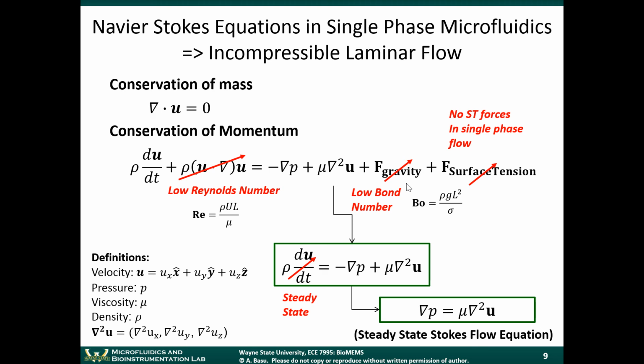So remember, with the Navier-Stokes equations, you can imagine packets of fluid moving through a channel. If you could add energy into one of those packets of fluid somehow, then you can get the fluids to move. So we're going to talk about dynamic micropumps, which are basically based on that principle. You add some type of additional force in addition to just what the Navier-Stokes equations are talking about. So in the case of a centrifugal micropump, we actually have a centrifugal force that's added into the Navier-Stokes equations.